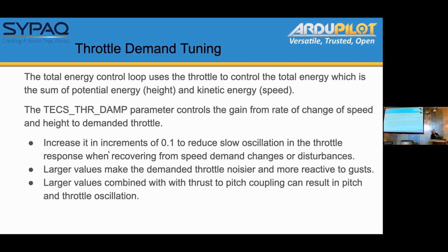But it does make the throttle noisier and more responsive to gusts, because the throttle is now responding to the rate of change of speed. Speed is noisy, and rate of change of height.